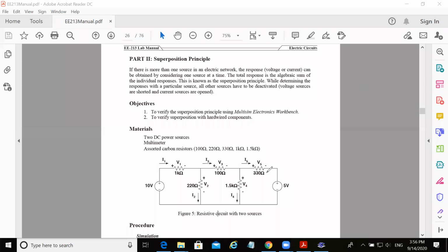What I mean by removing the effect of this source is that I want to make the potential between these 2 points 0. Why is that? Because right now, because of this source, the potential between these 2 points is 5 volts. Now, if I want to remove its effect, it is as if I want to make this effect 0 volts, right? And that is only possible if I remove it and I short circuit these 2 nodes.